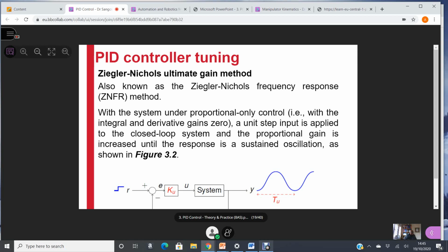There is amplification, but all that is taken care of in the tuning rules. Basically, you just get this sinusoidal input. It's got some amplitude, but you're not really using the amplitude for your tuning. All you are using is the period of the oscillation of the sinusoidal wave.